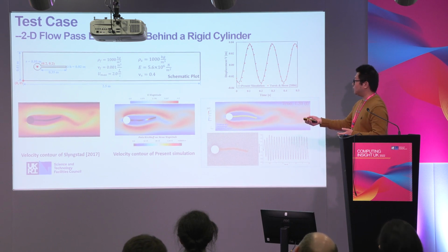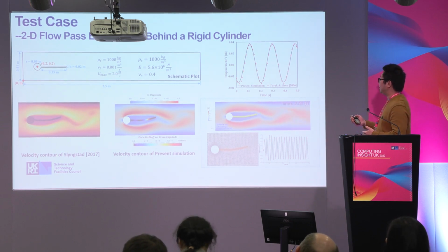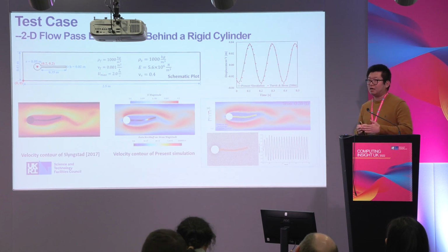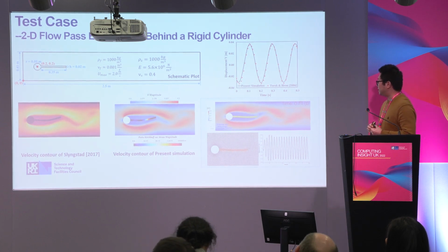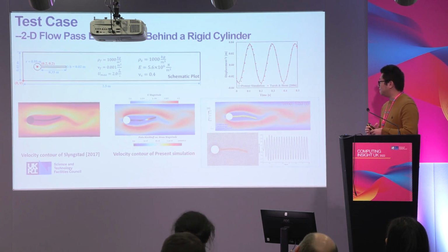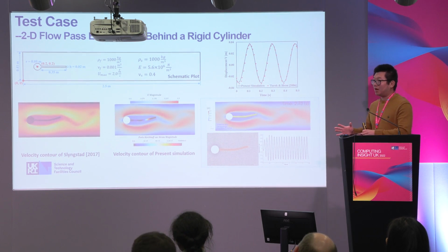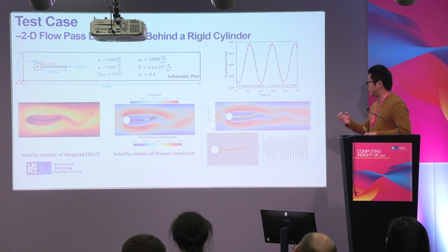And as you can see, we compared our velocity domain with the literature. And we also carried out quantitative validation with the displacement of the tip of the beam against the published data. And this animation shows how the domain is deformed. For the deformation of the domain in both the CFD part and the CSM part, I use the arbitrary Lagrangian-Eulerian method to tackle the mesh motion.